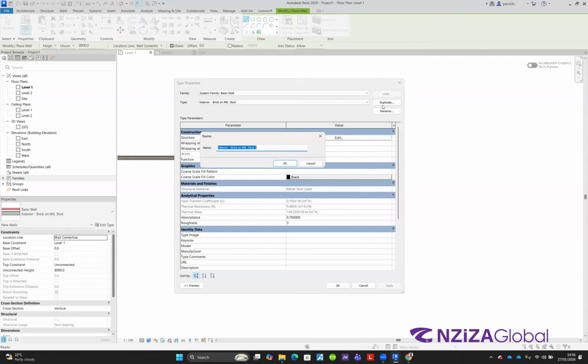So now I have the brick wall. I'm going to set a gypsum wall. I will start with Architecture, interior, gypsum wall. Then I click on, after naming, did you see this table for naming?